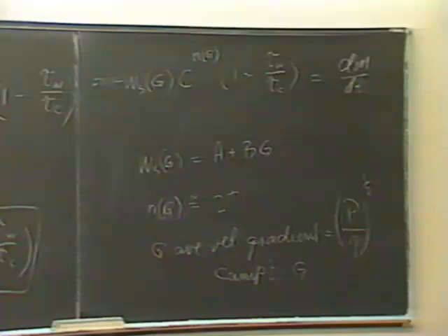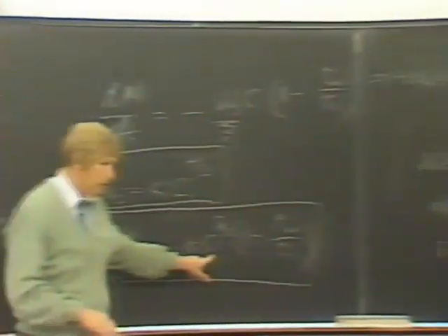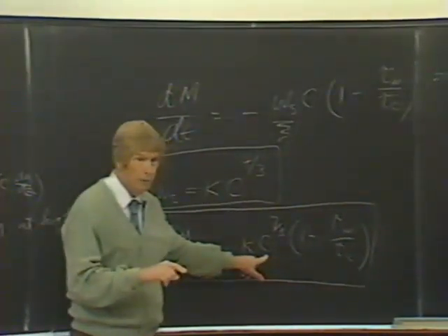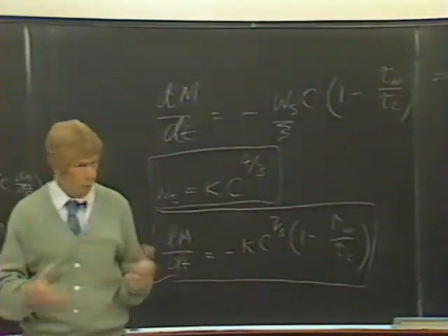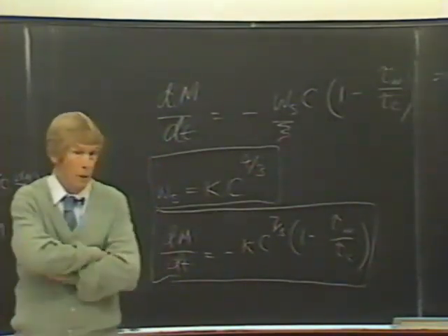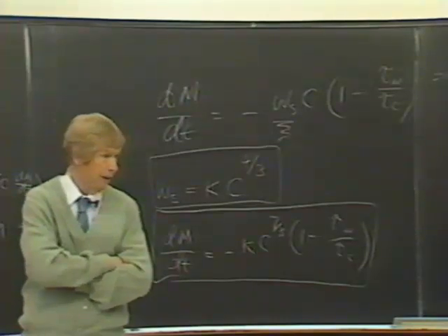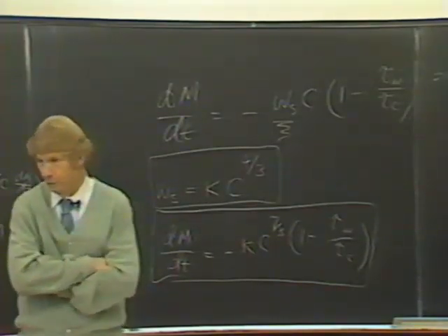Another way to do it is to simply go out and adjust your parameters until you get what you saw. We have two parameters. One is this tau critical, and the other is the W sub f. I have recommended to modelers that they go out and measure the settling velocities of particles near the bed to get their actual settling velocities. And you do that by lowering a tube horizontally. I'll draw you a picture of it.